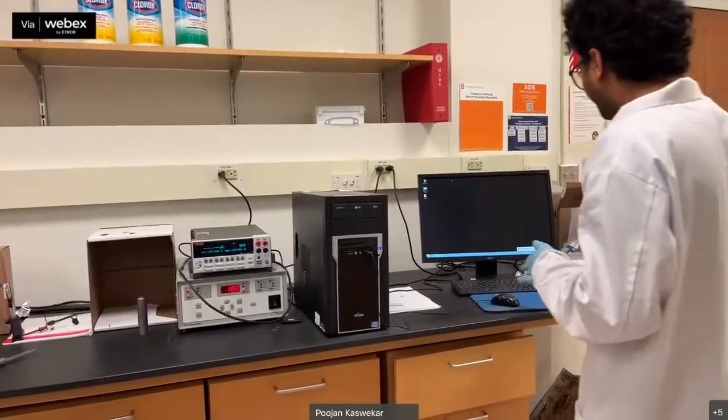Basically, there is a quartz crystal, and this quartz crystal is vibrating, and when material is depositing on it, the resonance frequency is changing. Once the deposition is very high, we cannot use it again for multiple uses, because the resonance frequency has shifted too much. Up to one limit we can deposit, depending on the material also. If we are depositing, for example, a few nanometers, then we can use it for a longer time.